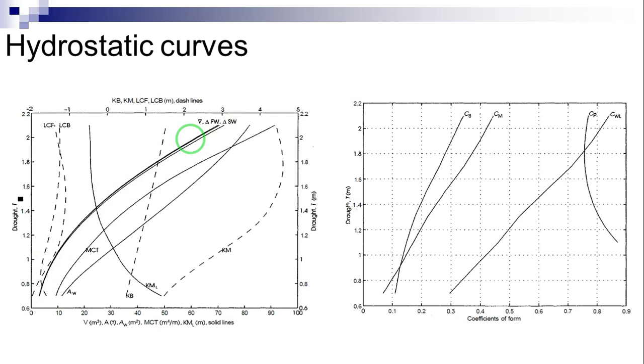In a single screw cargo vessel, the volume of all appendages is usually slightly less than 1% of the molded volume, and the shell plating is by far the largest contributor, perhaps 75%. For very large ships, this percent tends to be lower, less than 0.5%, for a typical large tanker. In multiple screw vessels, the appendages constitute a greater percentage of the molded volume than in the case of single screw vessels.